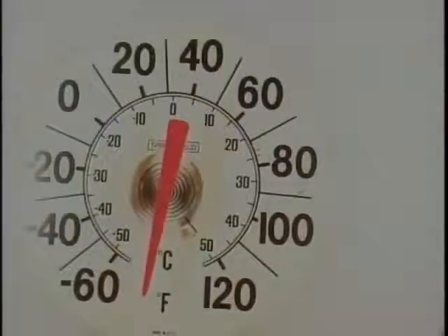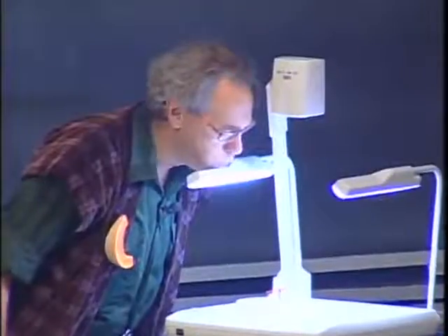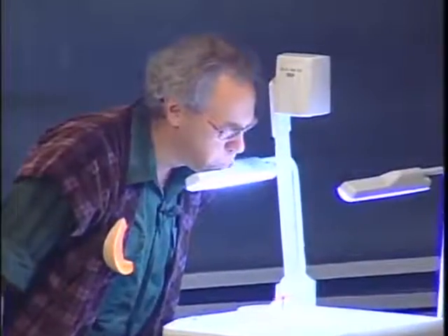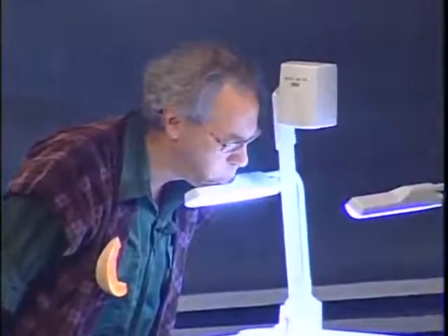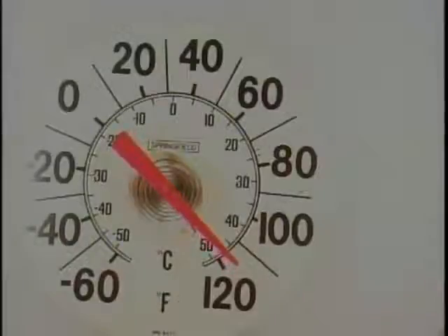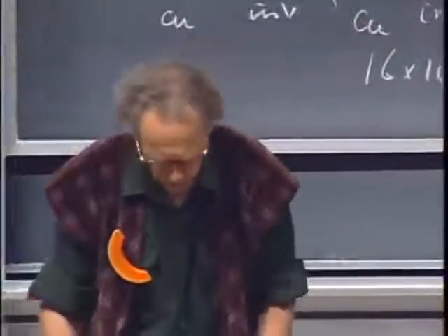So when I heat it, the bimetal tightens up more, and when I blow air over it, I can actually make it cool a little faster than it will otherwise. So as simple as that. Very simple device with the bimetals have many, many applications.